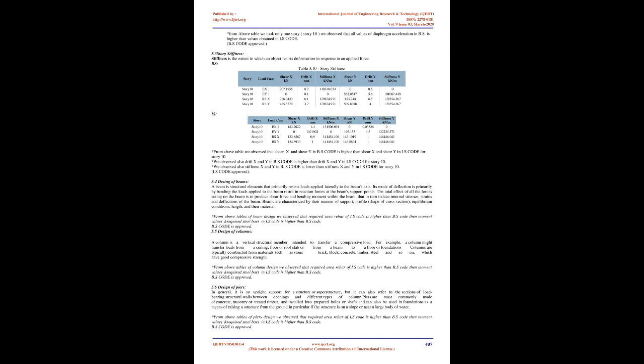Accelerations are needed to evaluate in-plane diaphragm forces in earthquake-resistant design of buildings, and for the design of their connections. Recorded floor accelerations in buildings during some past earthquakes have shown acceleration magnifications that are not properly considered by current building codes. Earthquake damage in some precast buildings seems to point out significant deficiencies in the design of precast diaphragms. BS: from the above table we observed that shear X and shear Y in BS code are higher than shear X and shear Y in IS code for story 10.